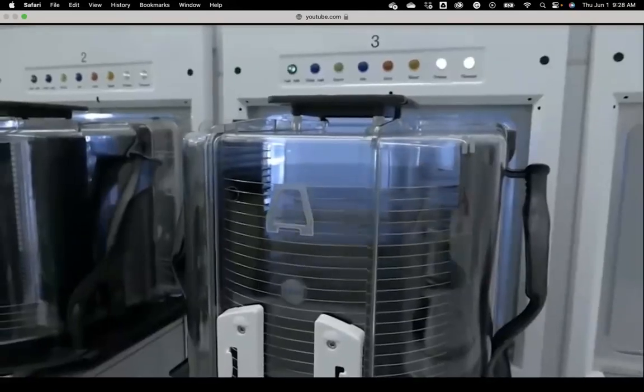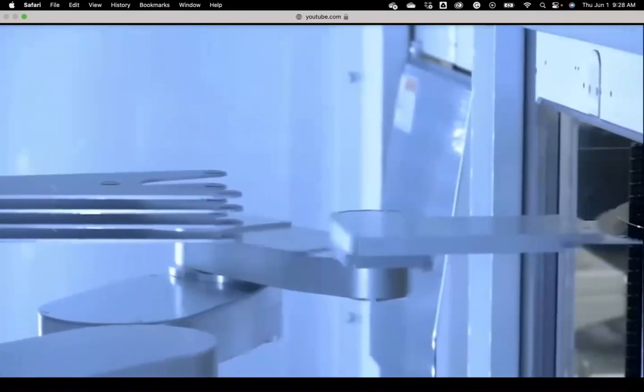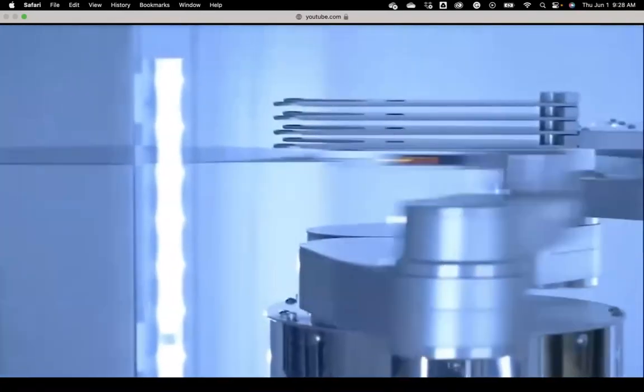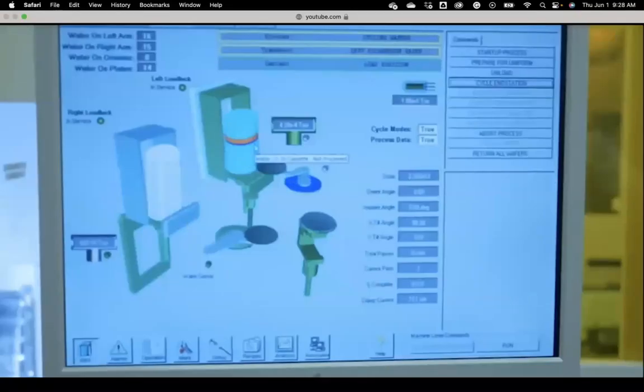The next step is the doping process, where impurity atoms are introduced into the exposed silicon. An ion implanter is used to shoot impurity atoms into the silicon. This changes the conductivity of the exposed silicon by fractions of a micrometer.